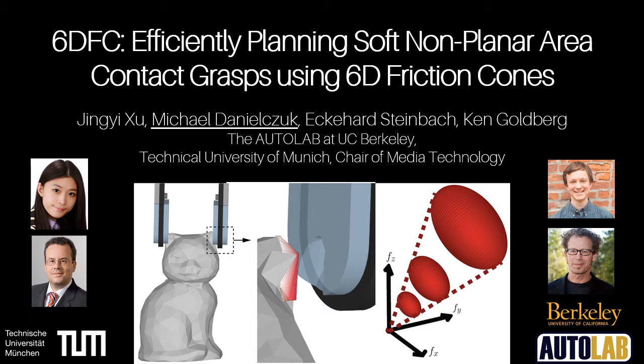Hi, I'm Mike Danielchuk. This paper addresses a common problem in robot grasping, false negatives due to overly conservative point contact models. We propose a new approach to more realistic finite area contact models based on an efficient formulation of 6D friction cones.